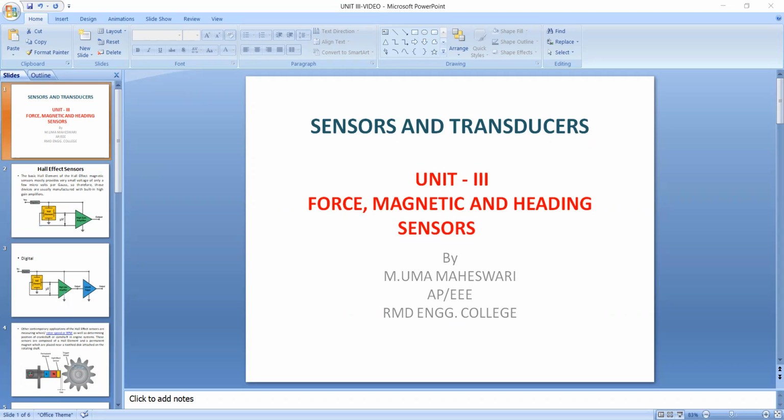The Hall effect sensor is a sensor which is used for detecting the proximity or behavior of a circuit, such as a motor, in response to a changing magnetic field. The Hall effect sensor is a transducer where the voltage varies by changing the magnetic field. This sensor consists of a metal strip. When it is placed inside a magnetic field, then in the presence of this magnetic field, electrons are deflected towards the edges of this strip. Then EMF is induced across its edges.